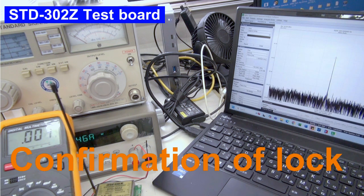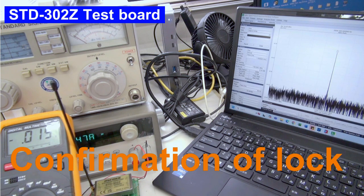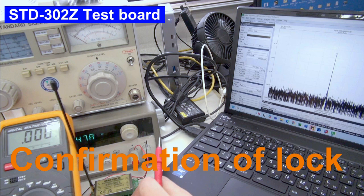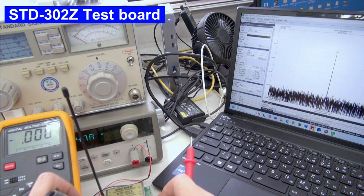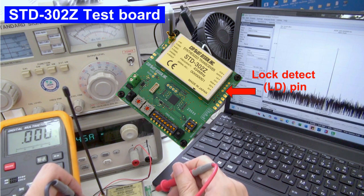If you want an electrical confirmation for the lock, perhaps as part of your control program, you can probe the lock detect terminal here. The terminal will go from low to high upon successful lock.